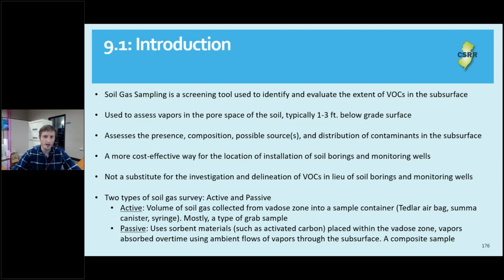Soil gas is not just generated from outgassing from a release. It is also generated by biological decomposition, chemical reactions, and physical decomposition. Soil gas is transported by means of molecular diffusion and convection. We in the department use the data for the location and installation of soil borings and monitoring wells. We also use the data for the design of remedial systems such as SVEs, and then the monitoring of them. You can also use it to monitor releases from USTs.